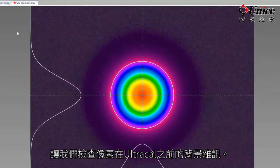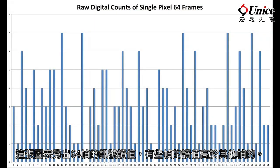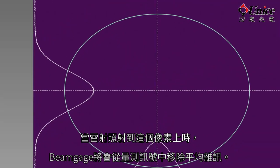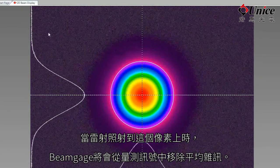Let's examine background noise from 1 pixel before Ultracal. This graph shows the values from 64 frames. Some counts are higher than others. Ultracal calculates the average of these counts and sets a true baseline. When the laser stimulates this pixel, BeamGage will remove the average noise from the measured signal.